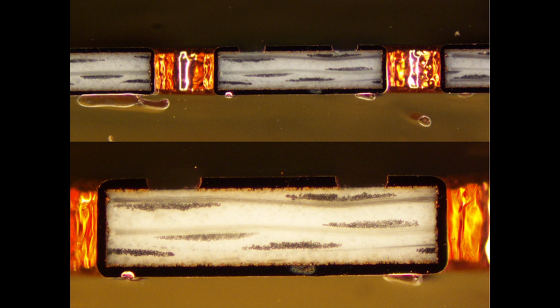And that's really because on the coplanar layer where you have the ground signal ground, the spacing between the signal and the ground is different if those sidewalls are parallel than when those sidewalls are angled away from each other. And the angled away would be the variation due to the trapezoidal effects. So that's one thing that needs to be considered with this type of structure.